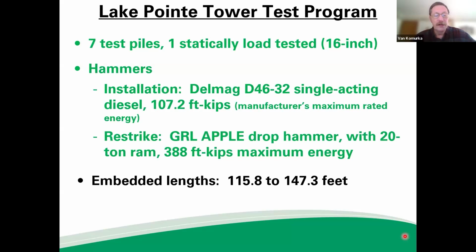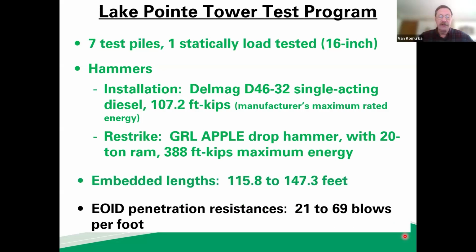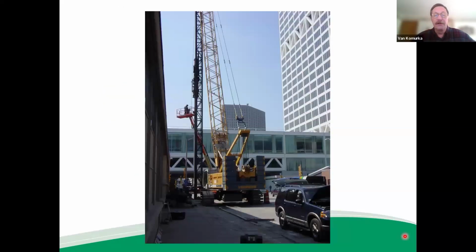of transferred energy. Embedded lengths of the test piles range from 116 to 147. And end of drive penetration resistances, not that much, 29 to 69. Again, not driving the piles real hard, not driving the piles all that deep. Pretty typical, or I should say, not outside the range of normalcy for pile driving.